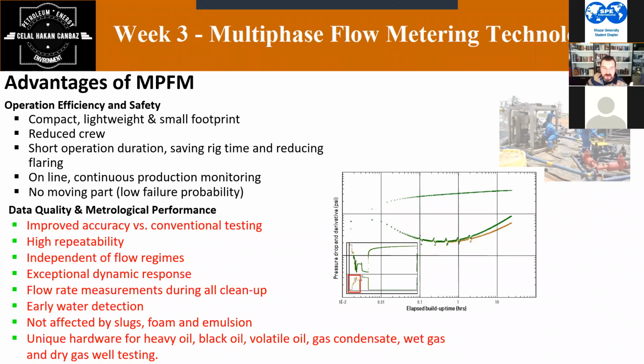When it comes through to your wellbore, your pressure will decrease, and your temperature will decrease as well. If you are producing from a retrograde reservoir, for example, somewhere between your reservoir and wellhead it will pass to two-phase flow. When it reaches your wellhead, it will be in two-phase.